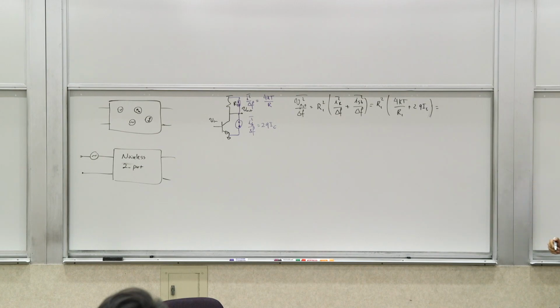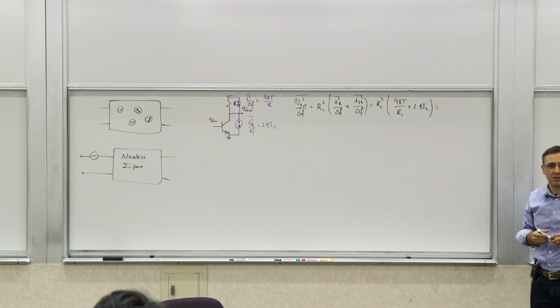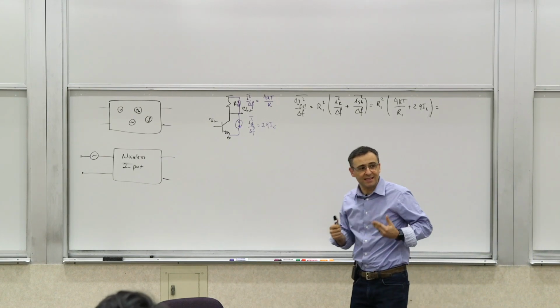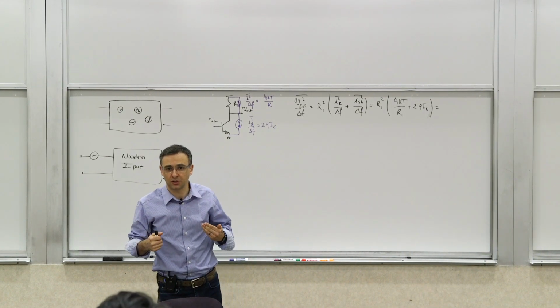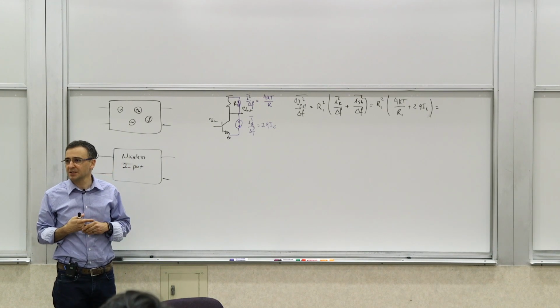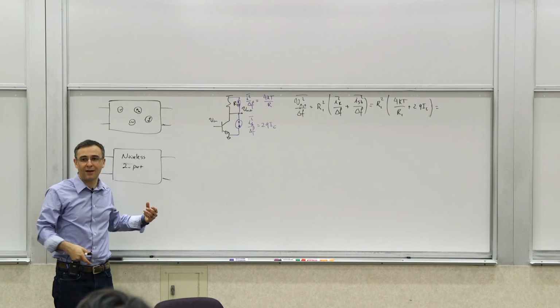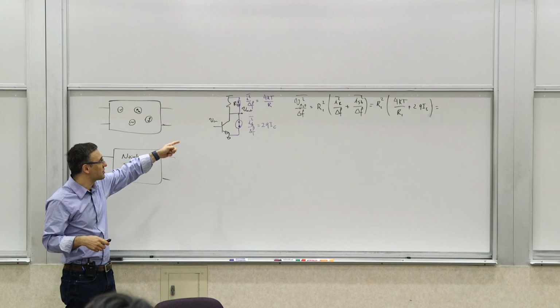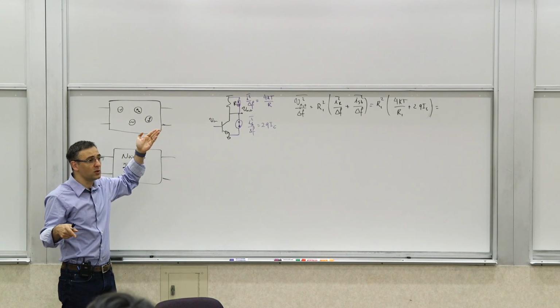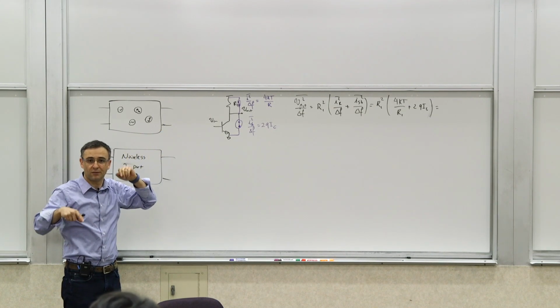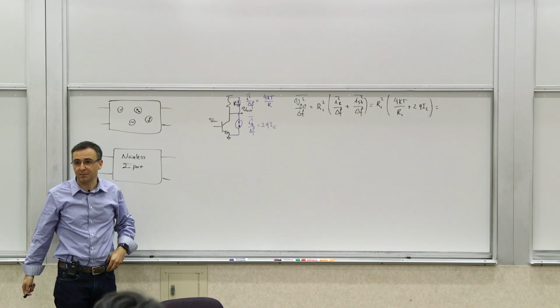You can multiply it out and get some numbers, right? So that's the noise at the output. This is real. This is something that you can go and measure. You have a sensitive measurement system, a sensitive spectrum analyzer, a very low noise amplifier that you attach there and put into a spectrum analyzer. This noise is present there. The fluctuation of the voltage will have this kind of spectrum.